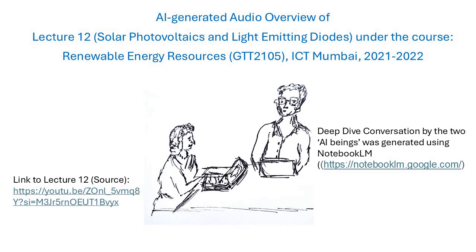So it's the same fundamental semiconductor physics, the p-n junction recombination that we've been discussing for solar cells, just running in reverse. Precisely. The energy released during recombination can manifest as heat, which is what happens in a regular diode mostly, or it can manifest as light. The efficiency of an LED in converting electricity to light is often quantified by its quantum yield. Quantum yield? Basically it's the fraction of electron-hole recombinations that actually result in the emission of a photon of light, rather than just generating heat. You want a high quantum yield for an efficient LED. Makes sense. And LEDs typically operate at fairly low voltages. Yes, usually within a voltage range of around 2 volts, depending on the color of the light being emitted.